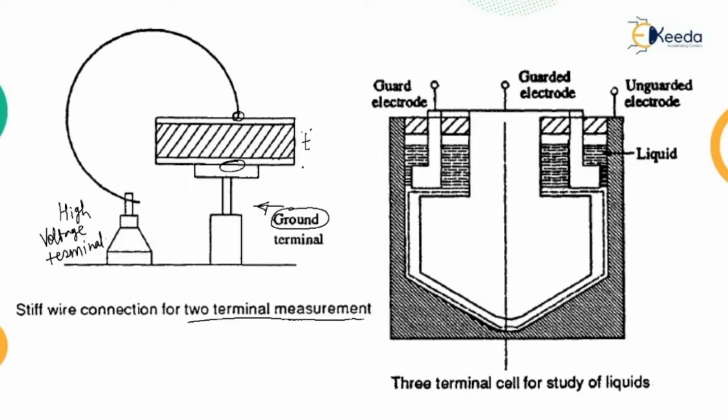Now, the measuring cell itself is the grounded support for the specimen, and a small solid wire is connected to the high voltage terminal of the measuring circuit. Now this is a simple and compact arrangement for quick measurements and requires less skill. You can see another arrangement.